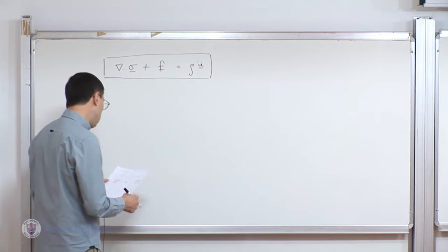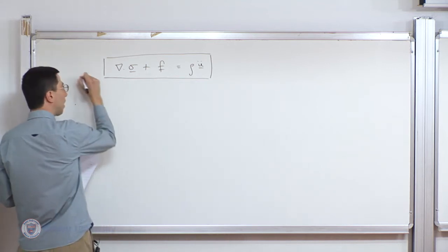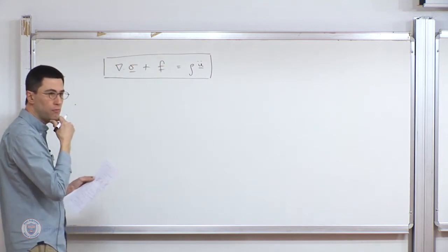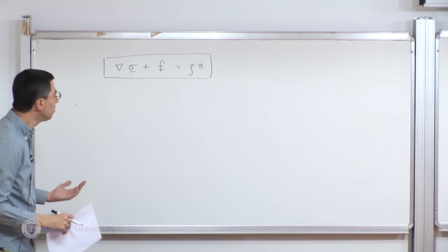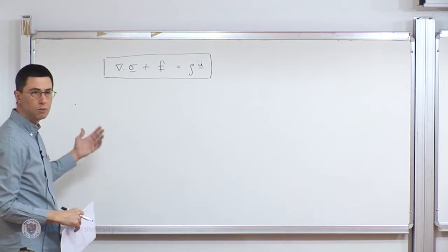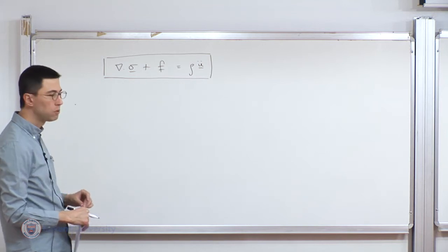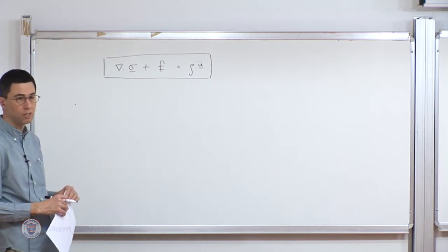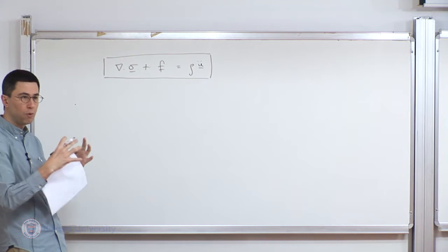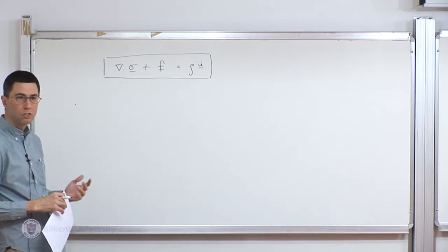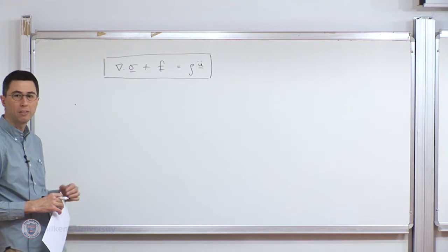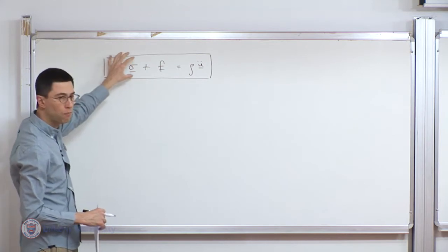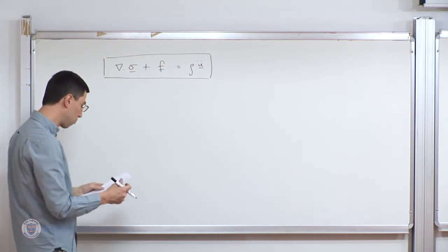So that's not something you need to memorize at all, but let me solve one problem where I make use of this equation, and eventually I will express the left-hand side in a cylindrical coordinate system. It really doesn't matter what it explicitly looks like, but we need to be able to interpret the individual components of the stress and their dependence on various coordinates, like we discussed last time, for instance, in a spherical coordinate system for a thick-walled sphere with internal pressure. We discussed which components are zero, which components depend on what, etc. Those interpretations we need to make. But once we have the form for the divergence, then with that interpretation, we can proceed with a solution.